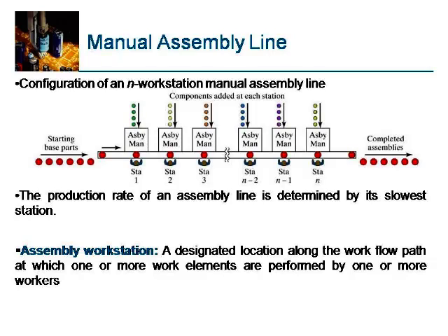The production rate of an assembly line is determined by its slowest workstation, because you have to set the speed according to the slowest workstation. That's how the slowest workstation only will dictate the entire line speed, and thus the production rate depends on the slowest workstation.